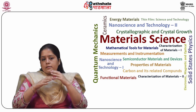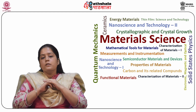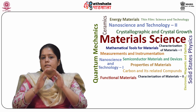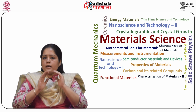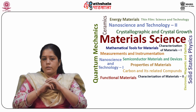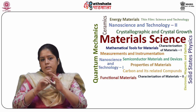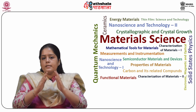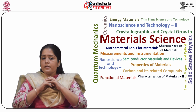Now let us discuss the effect of parasitic resistance. Solar cells generally have a parasitic series and shunt resistance, that is RS and RSH respectively, associated with them. These resistances act to reduce the fill factor, eta FF. Let us discuss the effect of series resistance RS.